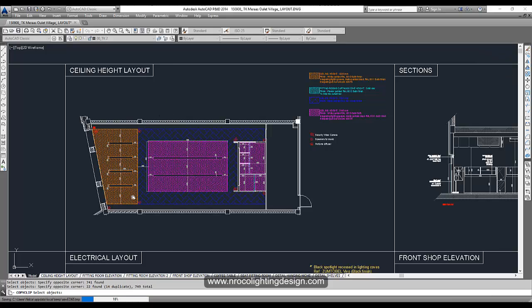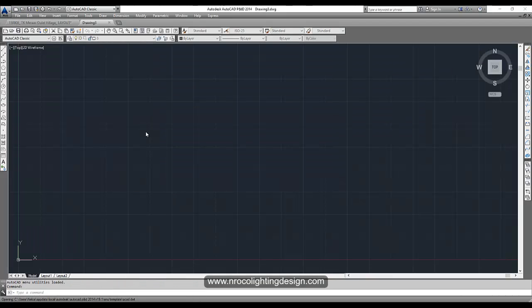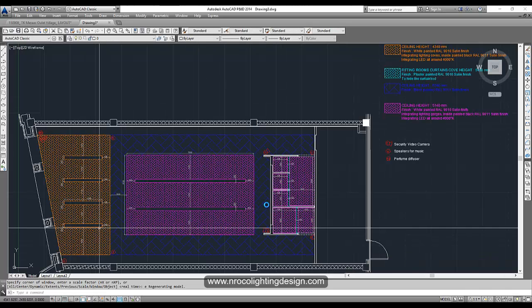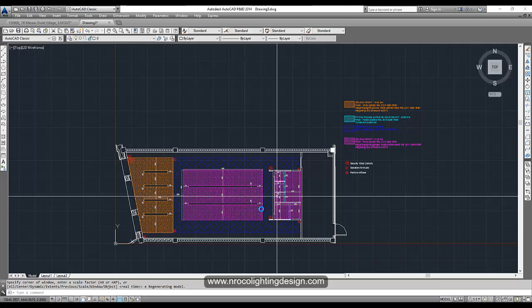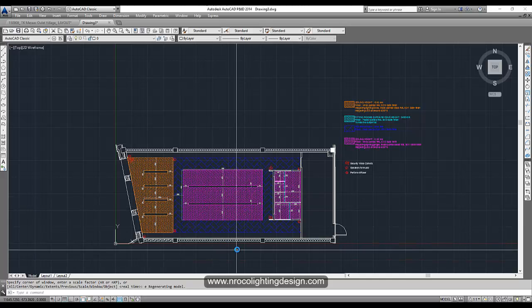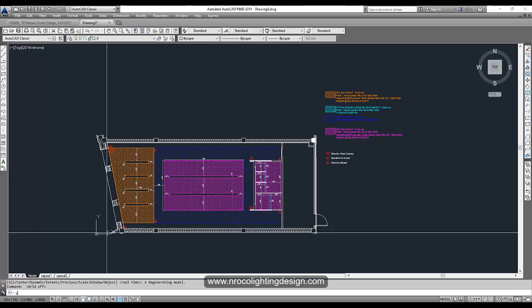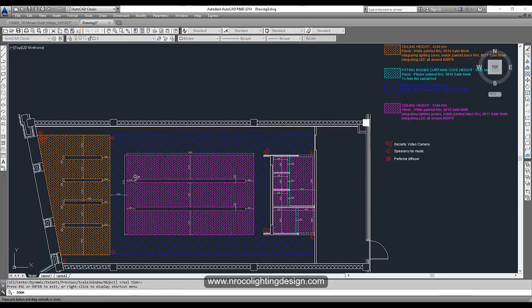And then right click and then open a new file. Control V, and then 0, 0, 0, enter. And then zoom extend. Z, enter, E, enter. That's the shortcut key for AutoCAD. If you want to know my shortcut keys in AutoCAD, I will sometimes mention what are the keys that I'm pressing. Just put a comment in the comment window below if you have questions.